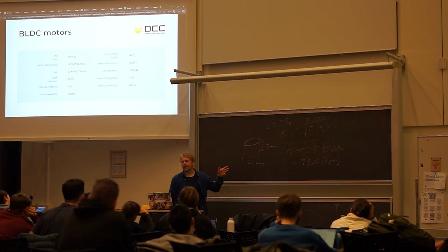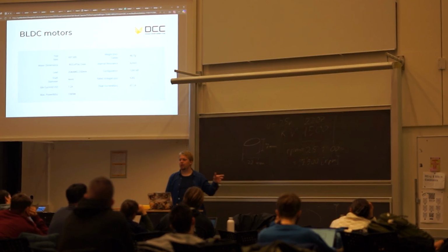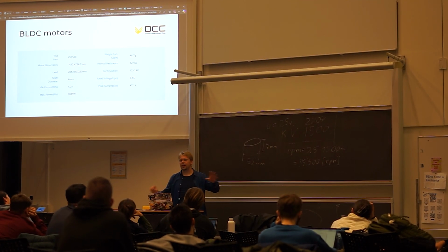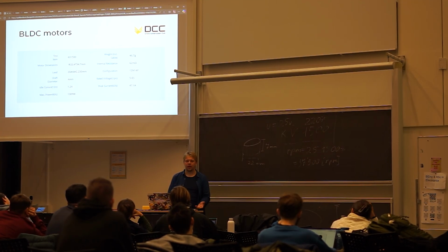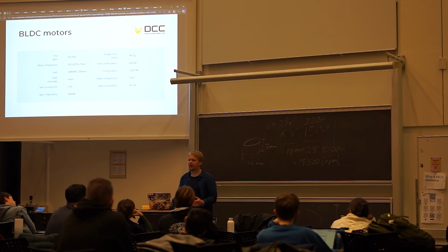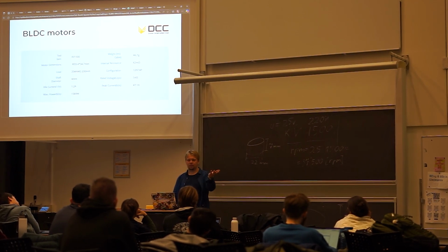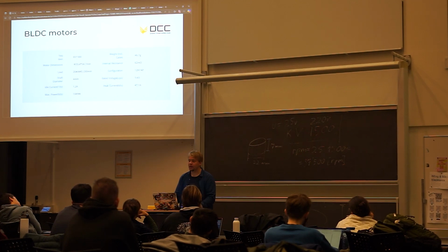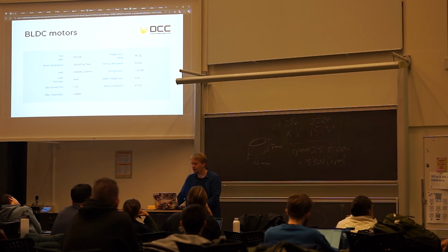The stator size kind of shows you how fast the motor can pull and how much heat it can dissipate. This changes very much by the construction of the motor. If it has an open top, closed top, are you having a lot of airflow? Did you put it onto a frame that has a plate right underneath or not? So can the air actually move through it?